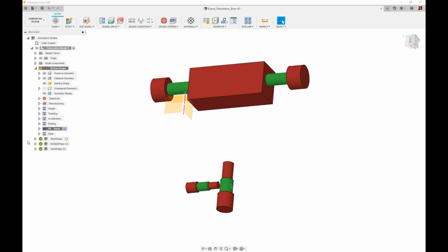In the first couple of analyses that I did, I'd go ahead and click the generate button, and then the outcomes start to get produced, and you can see them as they evolve. And I would go, oh, I needed another region that should have been an obstacle region. I didn't want it to build material there. Or I forgot to place preserves because I needed something in the final solution so that it can be bolted or connected to some other structure. I think it's just a different way of thinking for the setup of the model.